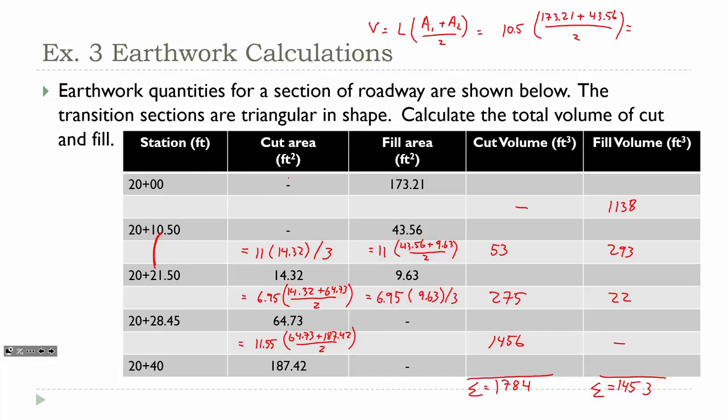So then if they ask what is the difference, like is this job going to have more cut or more fill, you can just take the difference of those and figure out which is going to have a higher amount, whether you're going to have to bring material onto the site or take some extra material off the site. Any questions on that one? Audience at home?